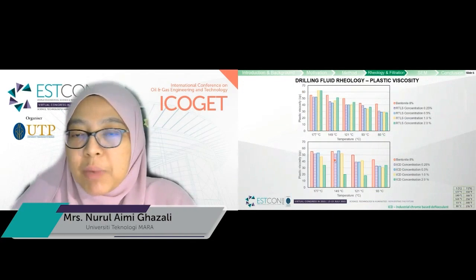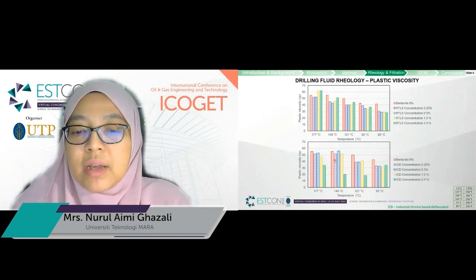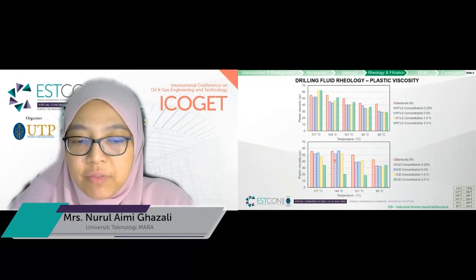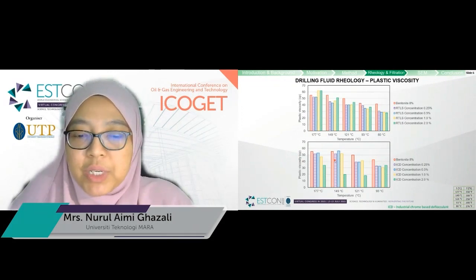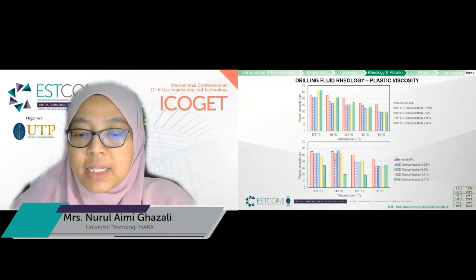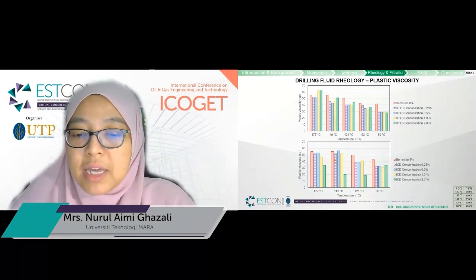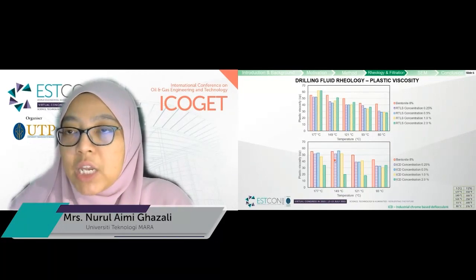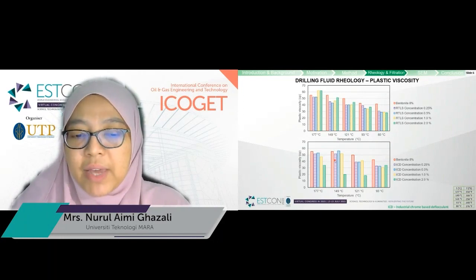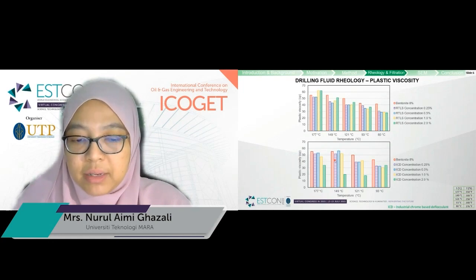Plastic viscosity is a primary function of viscosity. Ideally, the addition of the deflocculant does not reduce the PV. PV sometimes can increase due to the amount of solid content in the drilling fluid. Thus, there are small fluctuations in PV. But the high temperature condition does affect the PV as it gets higher at high temperature. Temperature agitation tends to allow further hydration of individual clay platelets and increases the viscosity as the volume increases. A small effect can be seen when the particles are large and relatively unhydrated.